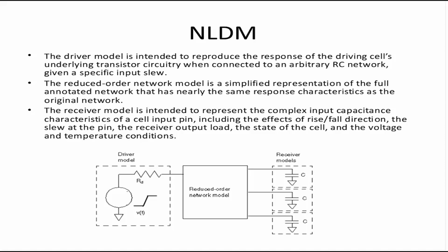So we should just know what is being used. You can go ahead and read about CCS, but the more important task at hand is how to define the constraints and make sure that a design is fully and properly constrained. That is the goal of STA. And the next step is to know how to solve the timing variations, before signing off.